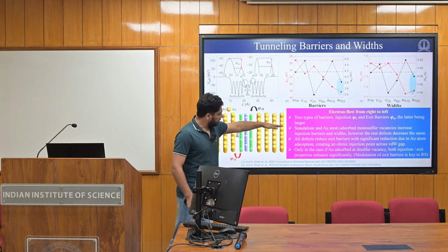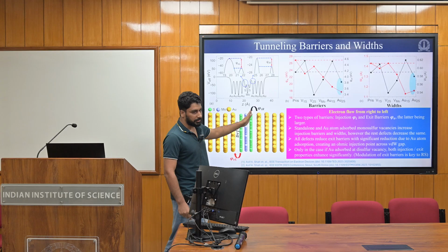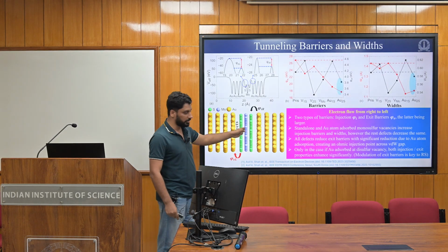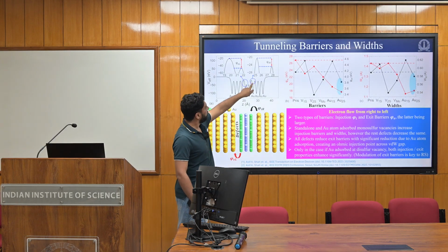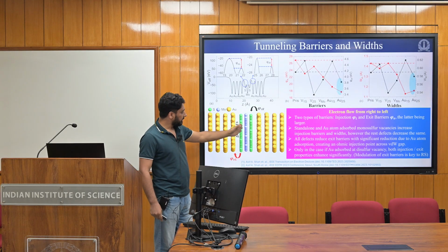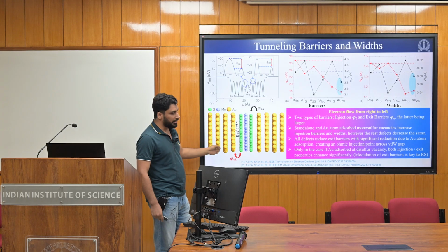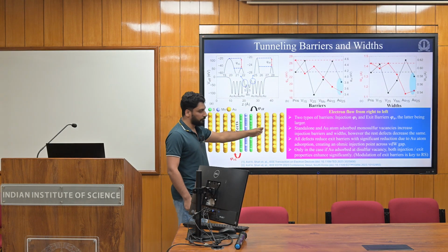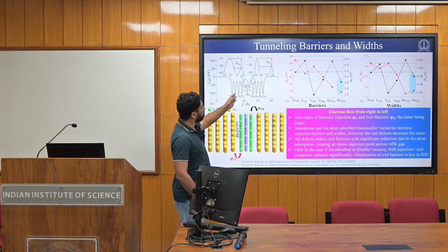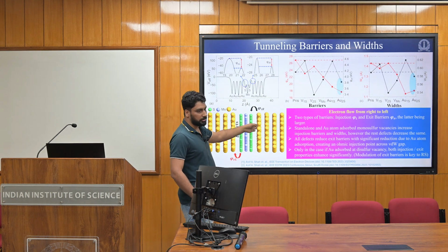An electron will travel smoothly through the gold. Once it comes to the interface, it will face a bump. This is what I call the electron injection barrier from gold into the MoS2. You can see that bump in the full potential, and it's shown here in the inset. Once it's inside the MoS2, it has to come back out and go into the other gold. That's what I call an exit barrier. So there are two kinds of barriers: it has to go into this and then come out of this. What I observed is that the electron exit barrier is the highest, higher than the electron injection